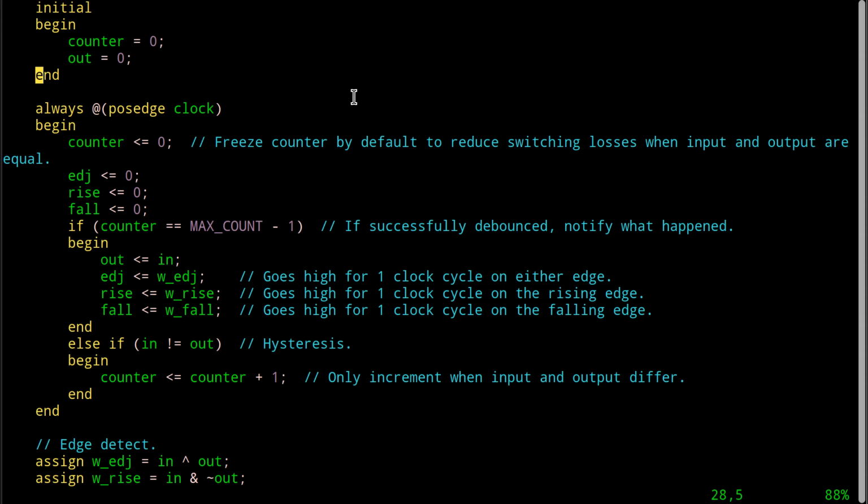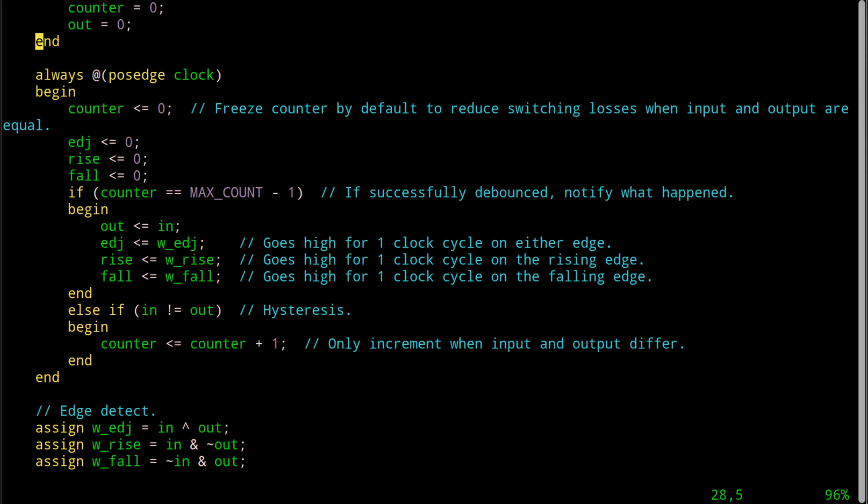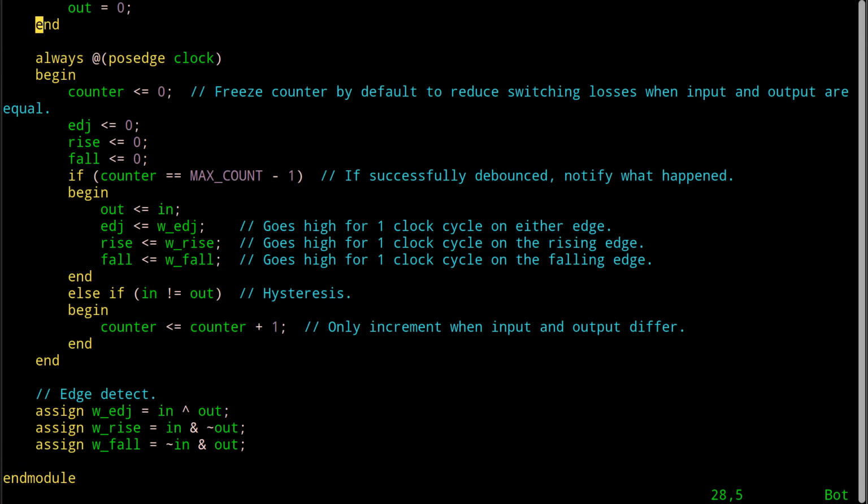And the reason you would do that is because you would want any simulation to be perfectly reproducible, no matter what the current input value is at the point in time the rest of your circuit got reset. Okay, so then this would always start up in the same way. As it is right now, this is not resettable unless you reboot the whole FPGA. All right, just a little side note. I don't care, and it's not a big deal, but it could be if you're in a large project. It's not the best style, is my point, to create these modules that cannot be reset along with the rest of your circuit. Okay. What is this thing going to do?